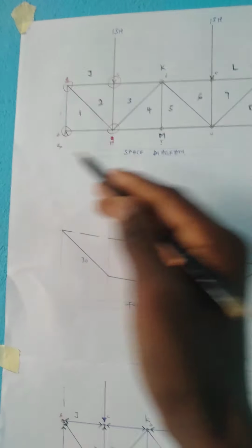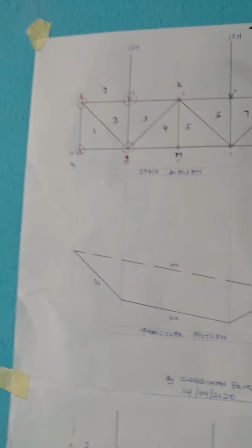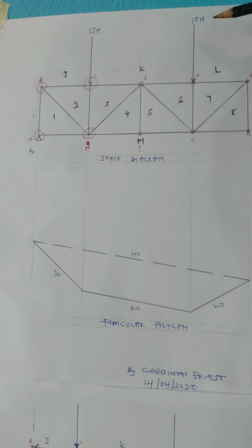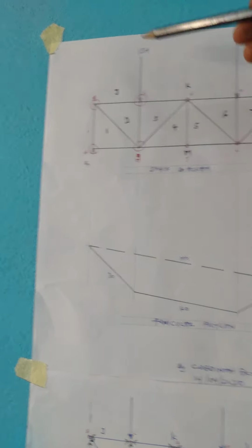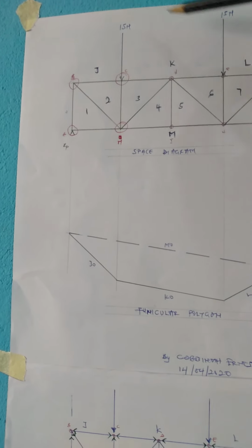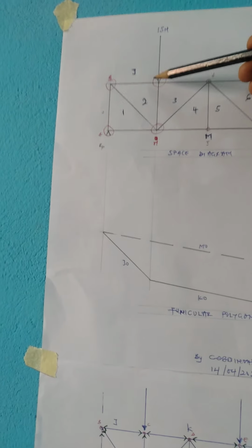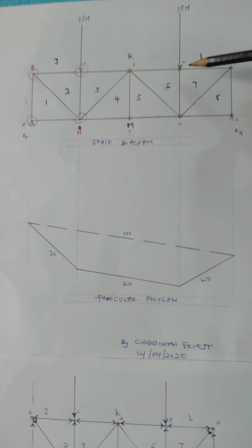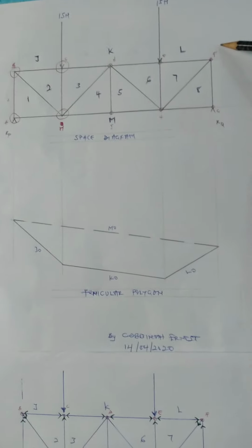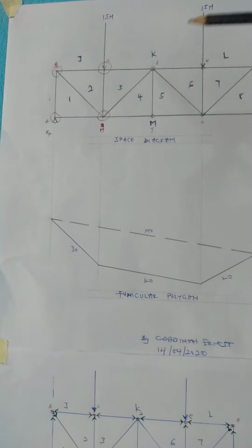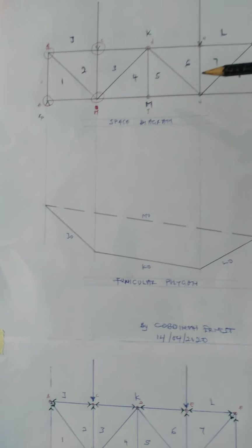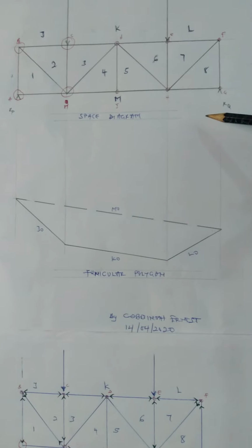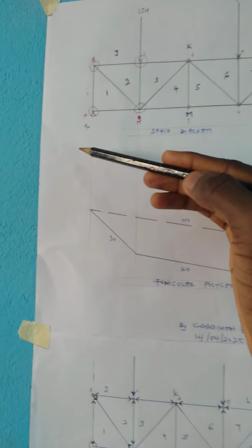And now we can clearly see, according to how the loads are being distributed, that it is a concentrated load or point load, meaning the loads or the forces acting on the truss act at a specific point, 1 and 2. It is not uniformly distributed across the truss. So it becomes a concentrated or point load truss, which is also a simply supported truss because the reaction supports are at the various ends.